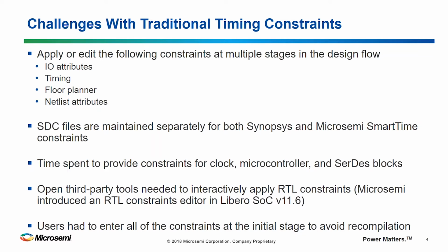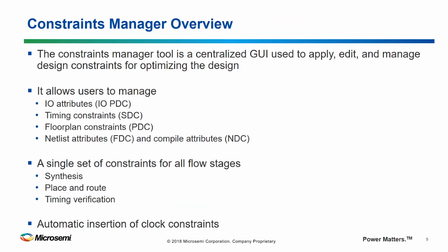We introduced RTL constraint editor in Libero SoC 11.6, but until we brought out the enhanced constraint flow, users had to enter all these constraints at initial stages of the design to avoid having to recompile, and sometimes you had to enter constraints in different tools at different times. So to address this, Microsemi introduced the enhanced constraint manager in Libero SoC 11.7.